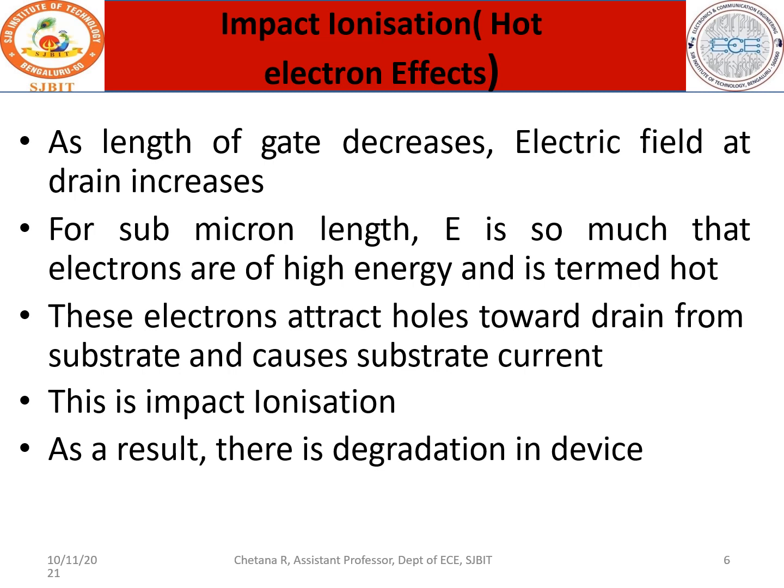These electrons attract holes towards the drain from the substrate and cause substrate current. So the electrons, which are of high energy, will attract the positive charge carriers present in the substrate and thus start conduction.